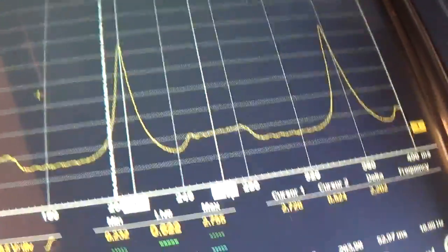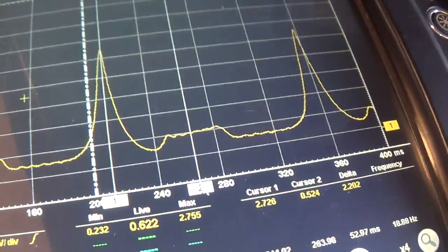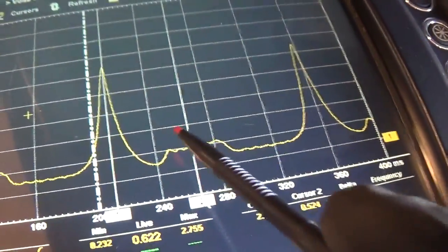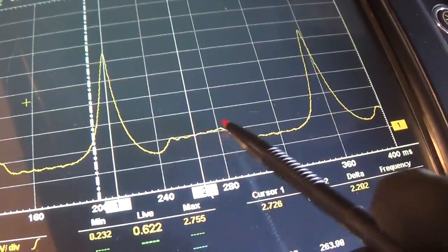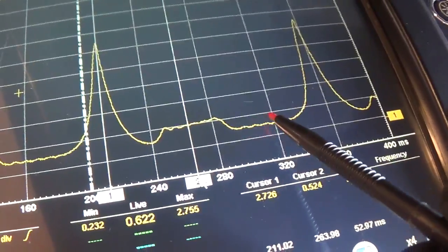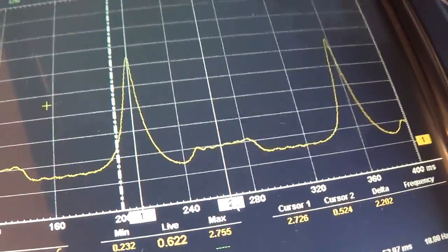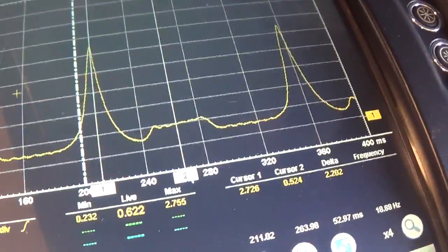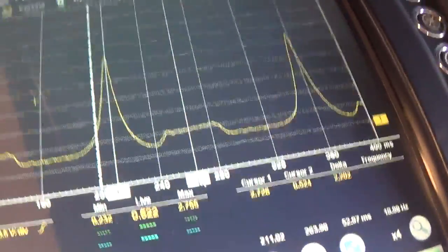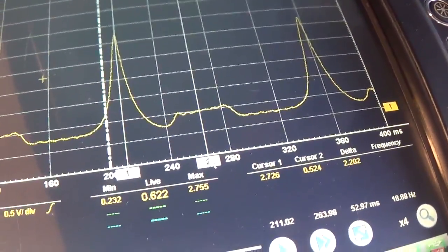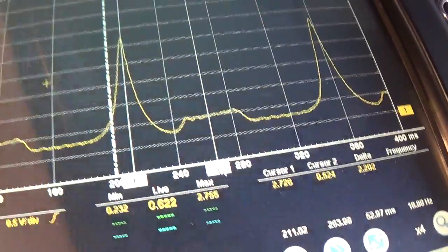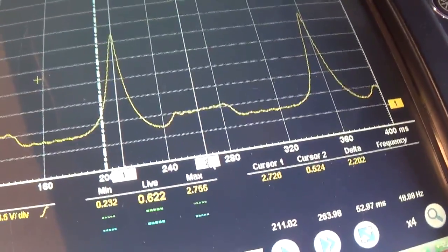Now we can break this up into the 4 strokes right here. Obviously we're at atmospheric, so that's the exhaust stroke. Then we can go back into the intake stroke, and then compression, power. So we have that saved. Now let's move to cylinder number 3 and compare apples to apples, like what we can see in cylinder number 3.